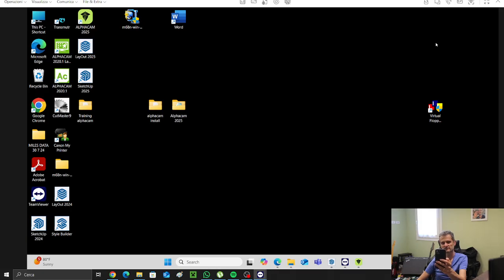Okay, so you can press F1, and on the bottom of the window you have compile. Compile, the bottom one. You go down until you are on compile, and then enter on compile. Okay. Generated. That's it. You can press escape up to the first page, Vision, and you can switch off.